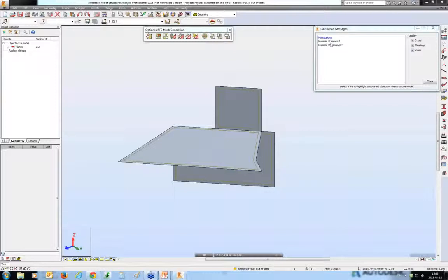If I have a model that has been meshed and I later apply a point load on that panel, which is not over a node, will the analysis pick this up after I rerun? Okay, so if you define the node in which you want to enter this point load and you remesh the panel, it will be recognized.